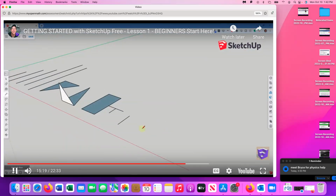And the most important one that you need to be aware of is when you have a tool active like the line tool, you need to be most aware of the ones that are indicating that you're drawing along a certain axis. And the reason for that is whenever you're drawing inside of SketchUp, you want to make sure you're drawing along an axis so that you can be sure things are coplanar.